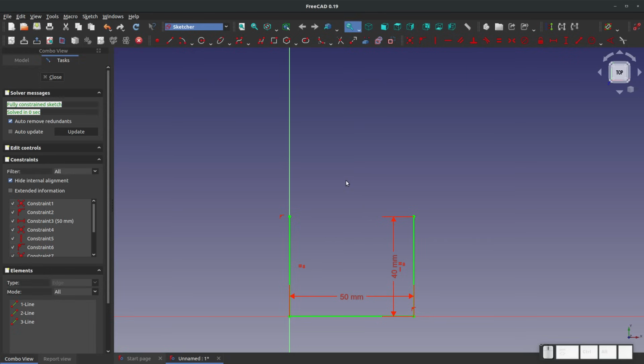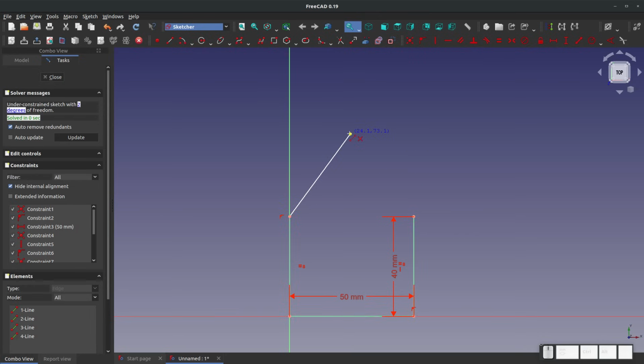What other things can we do with FreeCAD? If I go back to a normal roof, let's say I want a 90-degree angle on the elements of my roof, right? So I want a 90-degree angle between these two lines. Several ways to do that. I can choose this perpendicular constraint that I select both lines and they're held perpendicular. That makes sure that these are 90 degrees apart.